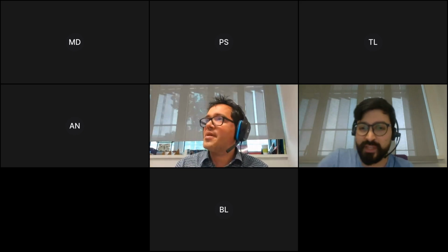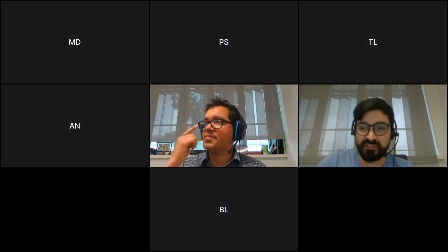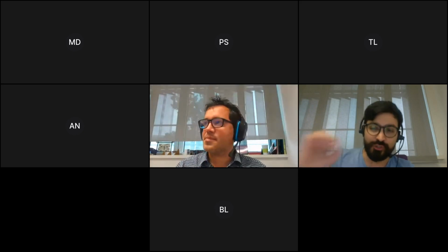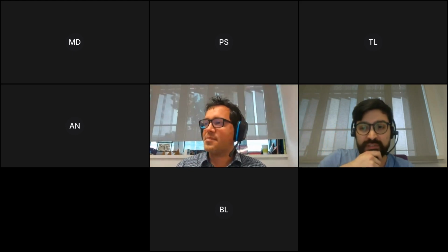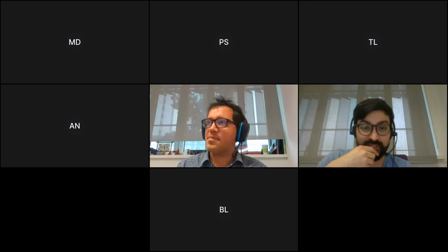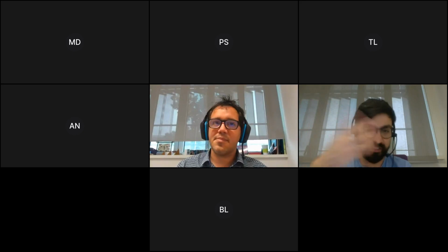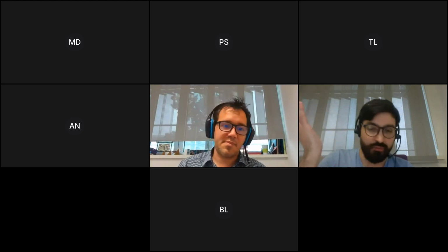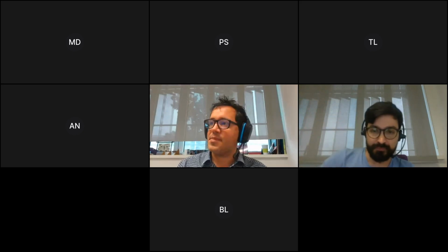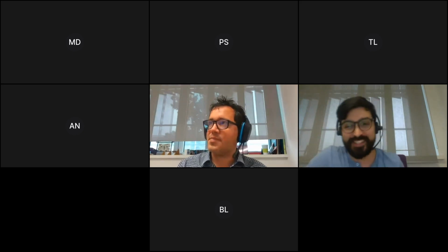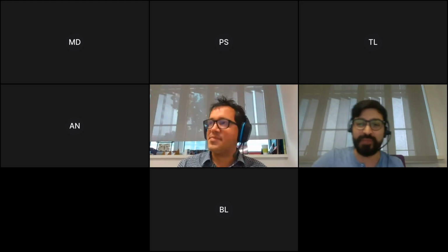I will read it. Mehdi says, you can export the mesh as Nastran, so a .bdf file that should be recognized by most of the software. Also, as the native format of COMSOL, .mphtxt, or as a matrix .mat, so you can convert it into the desired format in MATLAB. So I think Mehdi is saying, as Alejandro was saying, you just get the structural electrode from the platform that I already showed, and with Innov you can export to different formats that will be useful for your research. Yes, he agrees. He says that yes, .bdf or .mat works fine for me. Perfect.